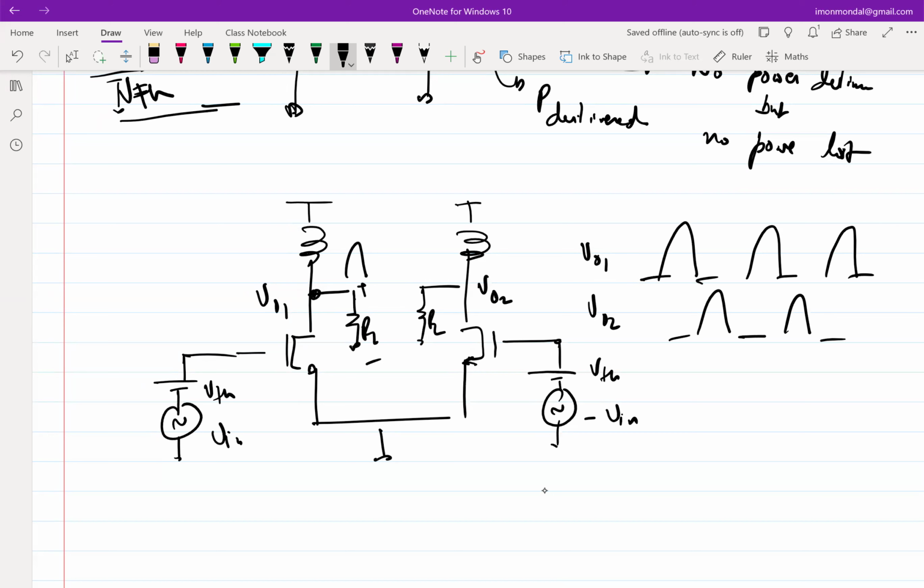So how do we subtract? Obviously, this is at the output. I'm talking about very large power. I do not want to use differential amplifiers and all. What is the easy way to subtract using passives? Using a transformer will help. Balun or a transformer.